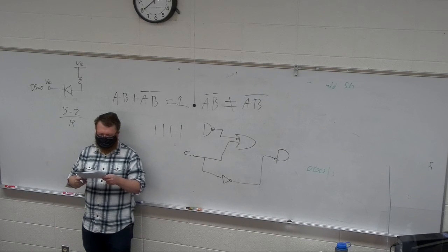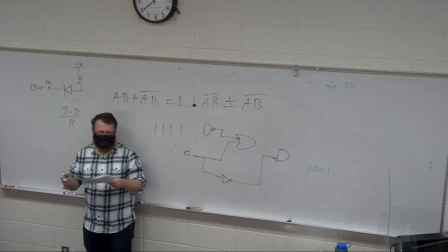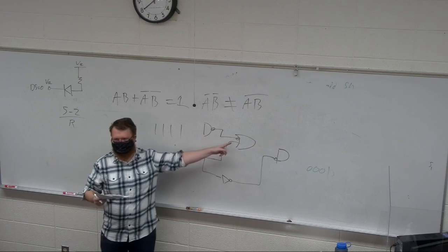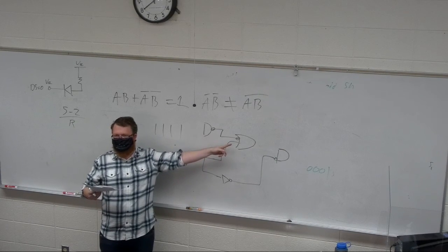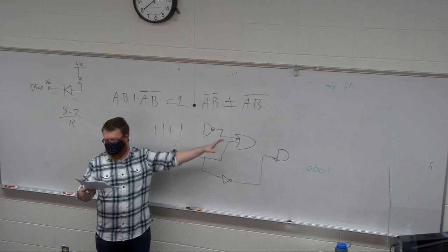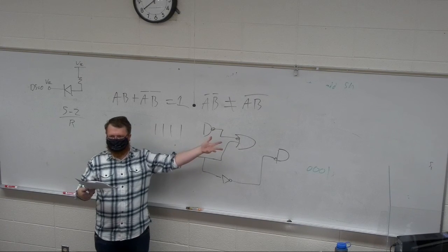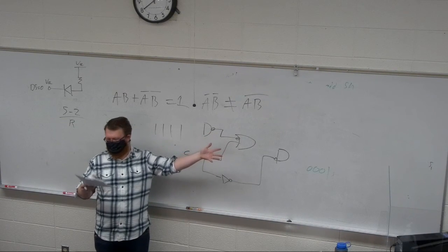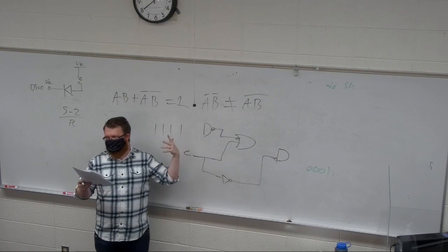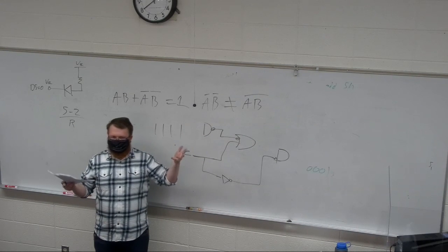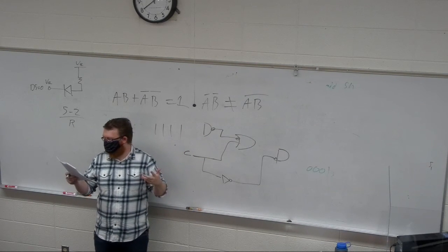And part C, I think hopefully by the end of today, it's just more of this, just push some bubbles around. And this one's really simple, part C, because it's only 2 levels. You have an AND gate, an OR gate at the output with AND gates behind it, and then you just turn both of them into NAND gates and you're done.